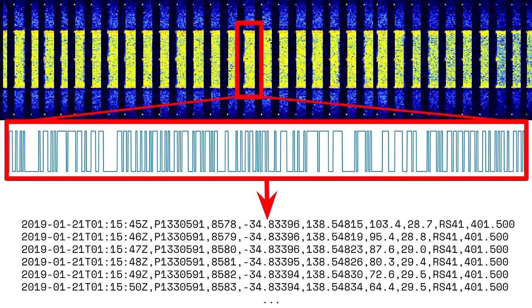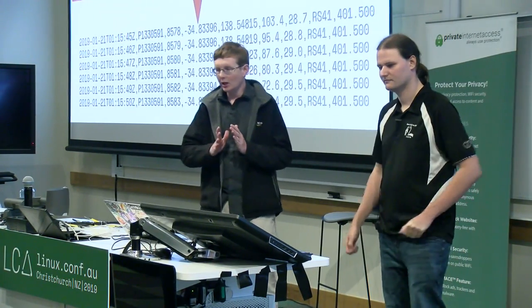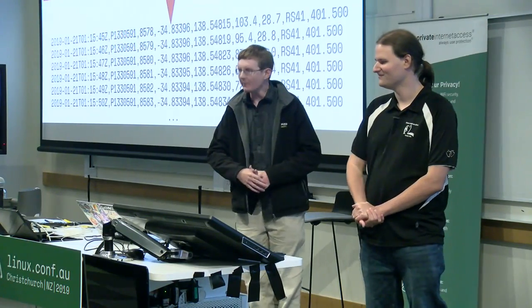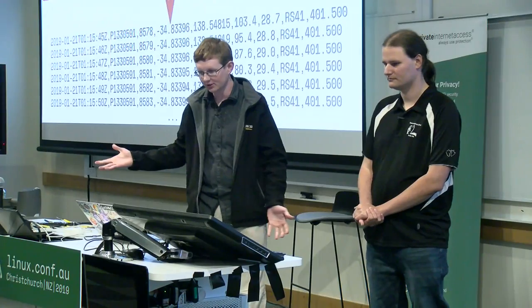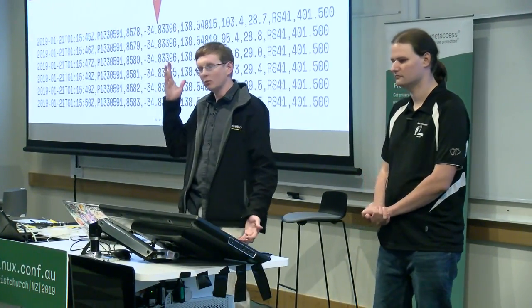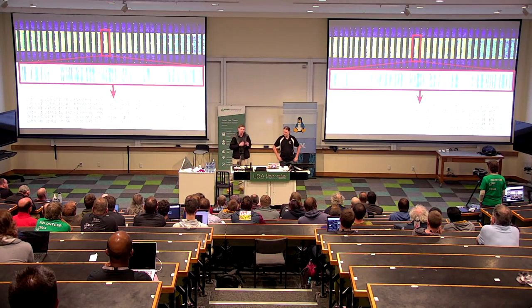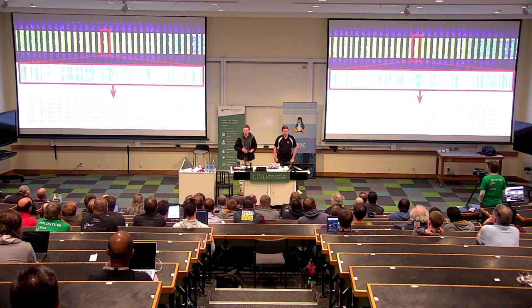So that's transmitted using frequency shift keying. That is where we represent zeros and ones by two different radio frequencies, and they alternate very, very quickly. In this case, 4800 baud, lightning fast. We get about 1 telemetry packet per second, which is more than enough for tracking the movement of a device such as this. On the screen, there's what we call a waterfall display, power versus frequency versus time. The yellow blocks show individual packets. We decode that to bits, and we extract the actual data from those to produce something that we can actually read, latitudes and longitudes and altitudes and temperature and things like that.